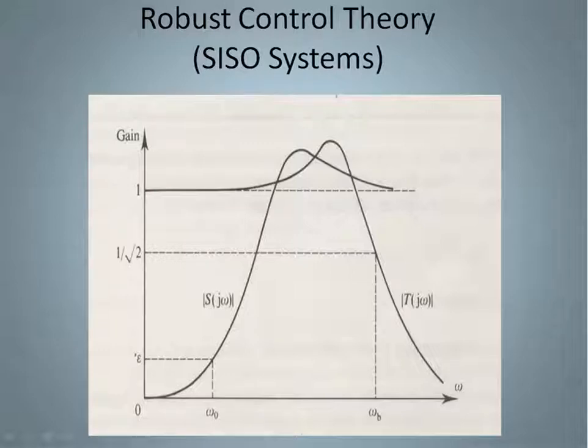In all of this we have done so far, there is a caveat. We have been talking about magnitudes without the other aspect of a frequency response, the phase information. Without the phase information, what magnitude can tell us is not conclusive. Therefore, in all our previous analysis, we need to assume that the magnitude plots correspond to stable systems, so our conclusions are valid.